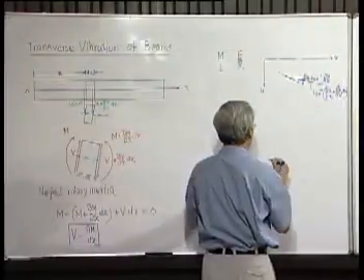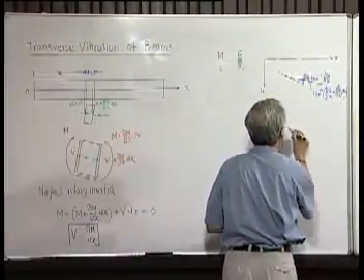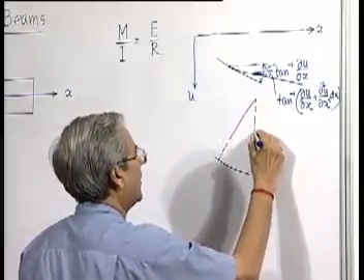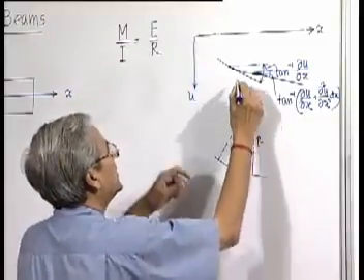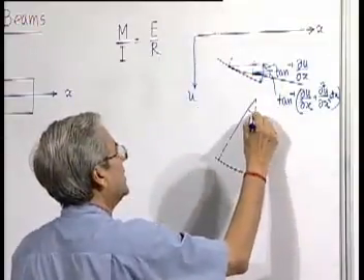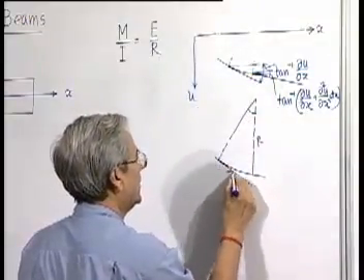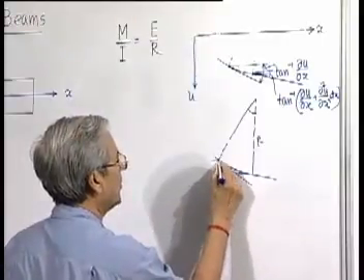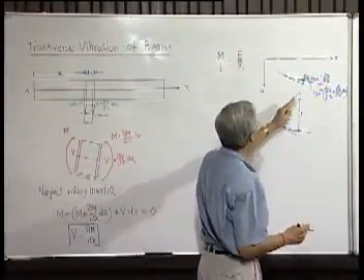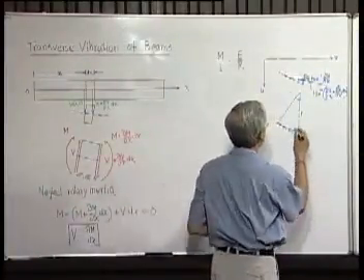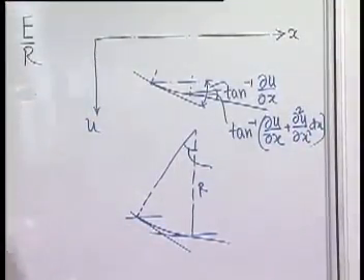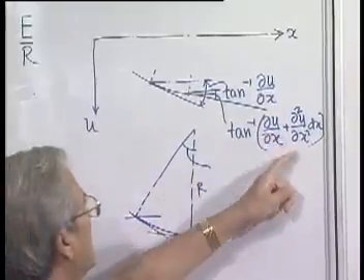Now, the only thing we have to keep in mind is that if we drop two perpendiculars to two different locations, this angle will be the difference between the slope at this point and this, or the amount of rotation, because this is also perpendicular to this. So, this is nothing but the difference in inclination of these two tangents, and that is given by simply this quantity.